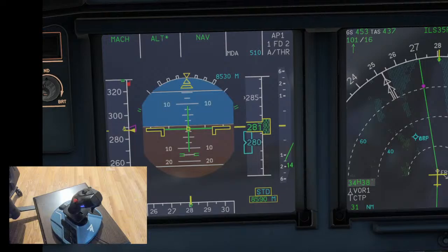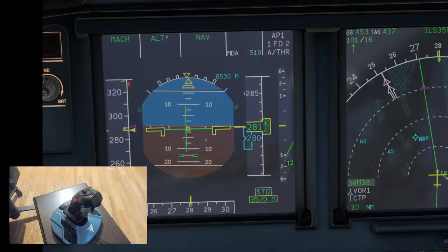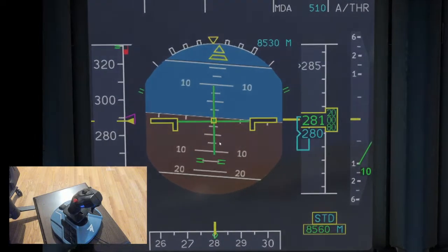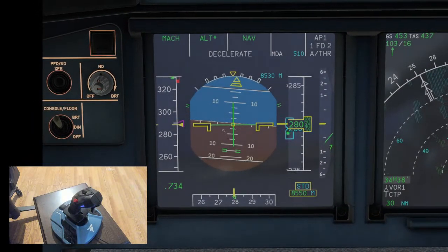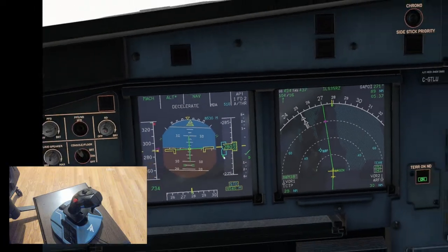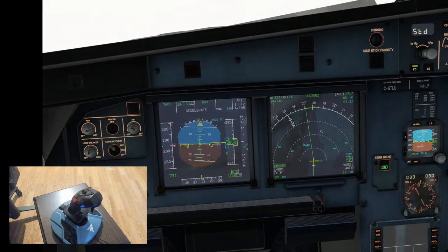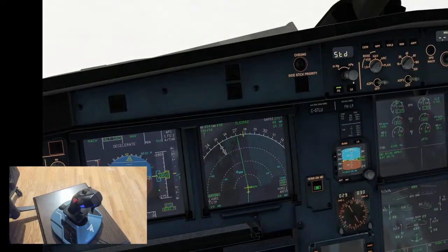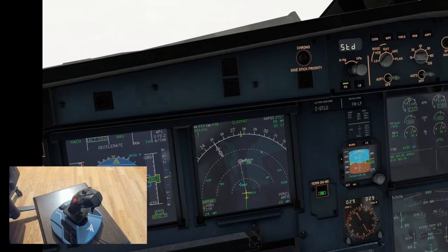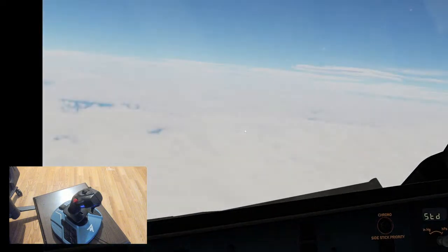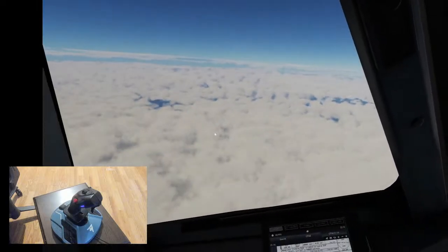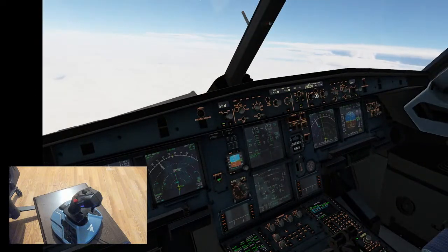This music is interrupting me, so I'm turning down the volume a bit. And as you may see, here is our flight director, which is turning slightly left. Now we are heading, and we are 90 miles away from the Gapti Point, so I'm increasing the scale here. And at the Gapti Point we need to be at 4,000 feet, so we can descend to 4,000 feet. Now I'm setting my altitude here.